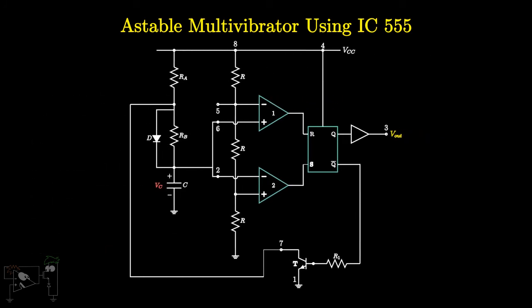Since we're using the RC network to control the timings and not the control pin, it is grounded by a 10 nanofarad capacitor to provide immunity from noise.